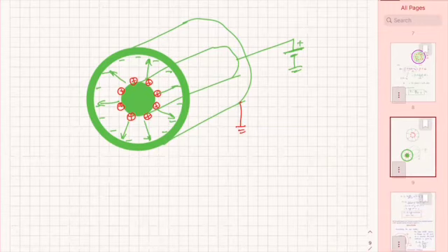Okay, so you have an electric field. The next time what we're gonna do is take that electric field, integrate it along a line to find the voltage. And then from the Q that we have and the voltage, we're gonna find the capacitance. And therefore we are gonna know the capacitance of a coaxial waveguide, as we call it, or coaxial conductor, or coaxial line, okay?